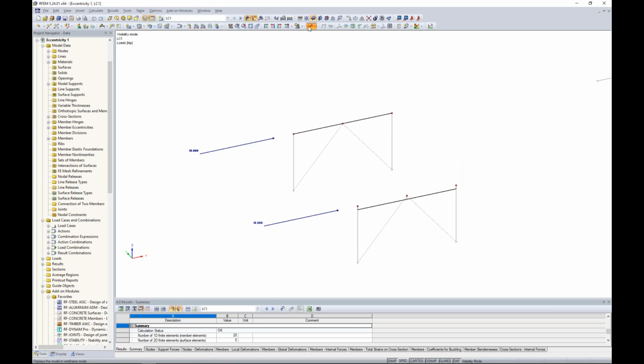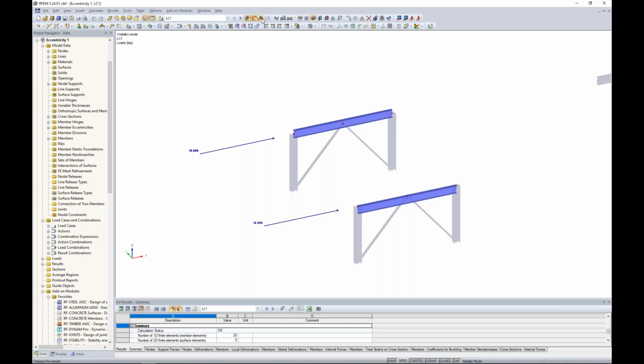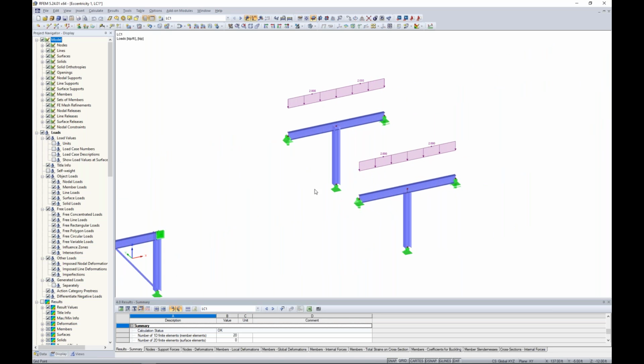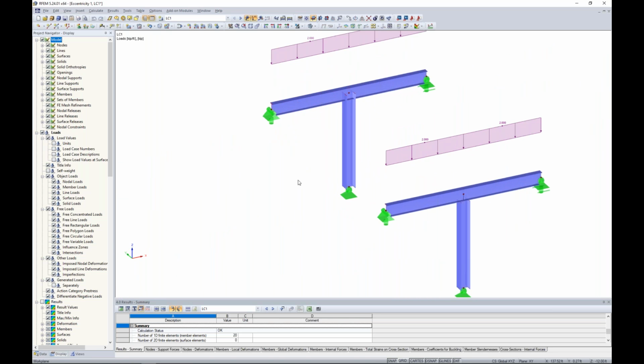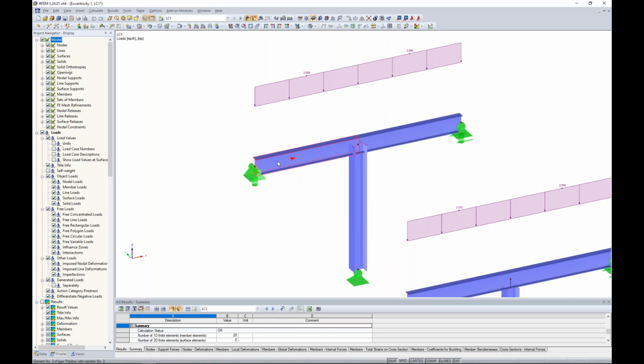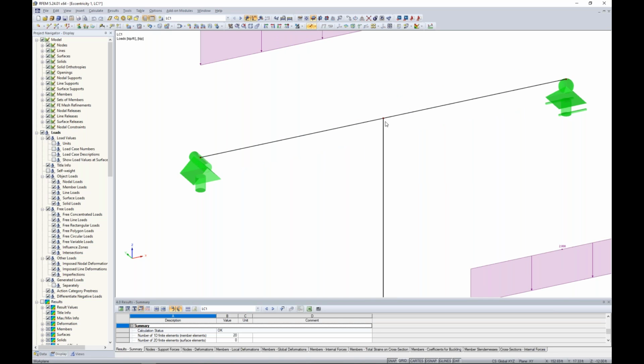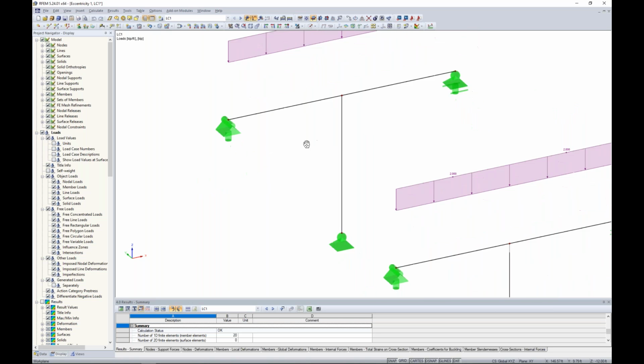So moving on to our final example in this particular model. We'll cancel our visibility mode. Let me once again turn on my nodal supports. We'll move over to the right here. Just a T-type frame. And with this system here, let's assume that we have these beams framing over the top of this column. And once again, my first example in wireframe view, everything's framing in at the center line here. So just default settings, no eccentricities.